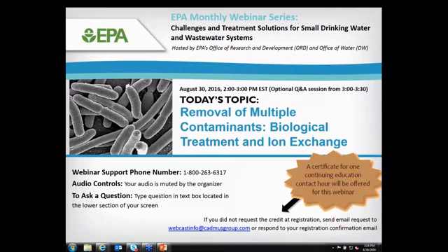And then what we found is we were finding really good correlations just between dissolved oxygen concentrations and nitrate removals. And once again, the Hach method was then backed up with different analytical tests that we split out in the laboratory. We found a good correlation between effluent dissolved oxygen concentrations and the efficiency of nitrate removal. So basically between dissolved oxygen concentrations with a dissolved oxygen electrode, which gives real-time data, and Hach tests for things like nitrate, we're able to do a good job.